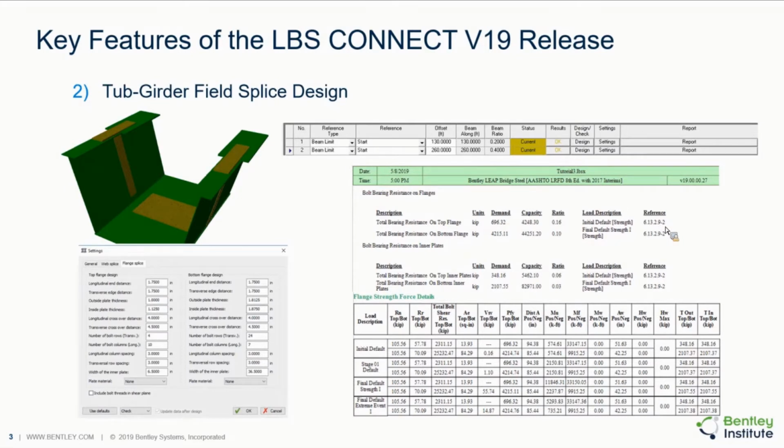Let me put it this way. So for a healthier design optimization, you should start with a conservative size. So if you start with a smaller size, with small increments, we increase wherever necessary, right? So if the flange thickness is a problem, we increase the flange thickness gradually. If the height of the section is a problem, we increase the height of the section gradually. But we never decrease the section. So currently, it's a good practice to start with a conservative section, but in the future, we will definitely find the most economical section if the section is extremely over-designed.